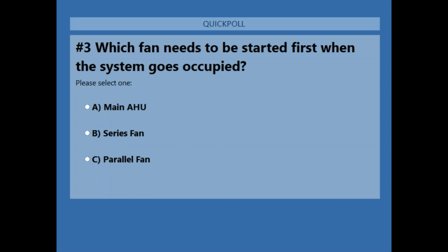All right, so Jessica says there's a damper on the primary inlet, but nothing for the plenum opening. That is correct. There's no damper on the plenum opening, nor is there one needed, because what will end up happening is the fan will be designed to do a certain amount of CFM, say 1,000 CFM, and if my cooling 55-degree duct is open to 800 CFM, it'll automatically pull the other 200 from the plenum. If my cooling duct is open to 1,000 CFM, it'll pull nothing from the plenum because the pressure will be higher on the cooling inlet side, so that'll be pushing things along, so it will not pull anything into that plenum opening.